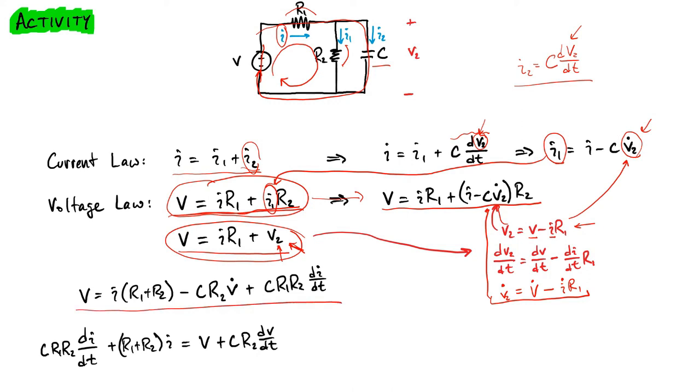We can rearrange it a little bit more now to specifically gather some terms in terms of, again, I, which is the state. So we're going to have a derivative. It makes sense that we have a derivative on I. And one of the interesting things, we haven't seen this very much yet, but this is an input. Our input is the voltage V on the source. And in this case, the dynamics that describe the current across the resistor require us to also have information about the derivative of the input. So that means that the evolution of the current I is driven not only by the voltage V, but by its derivative as well. And so that's something that we'll see more and more throughout the course, but it takes more sophisticated systems to see that.